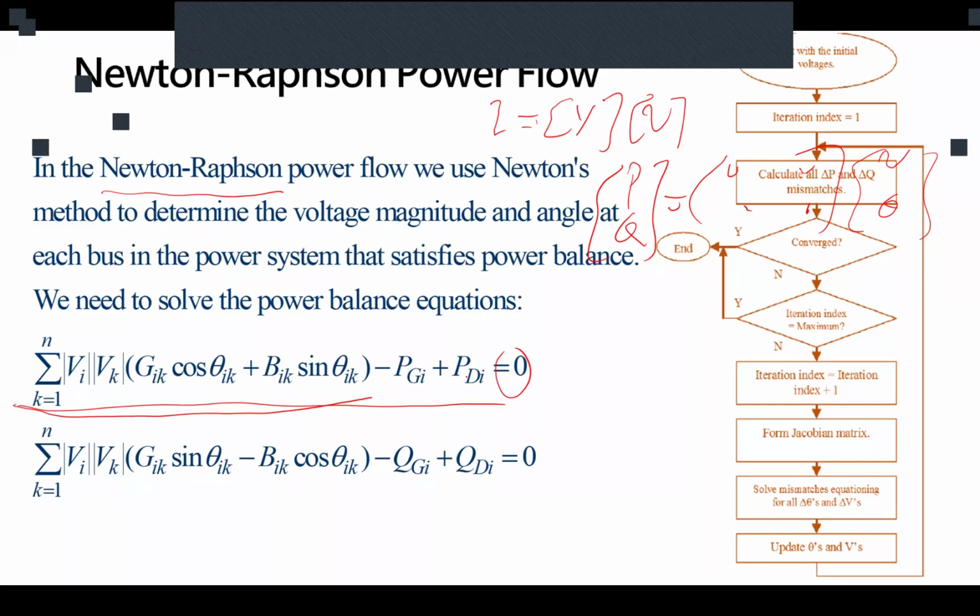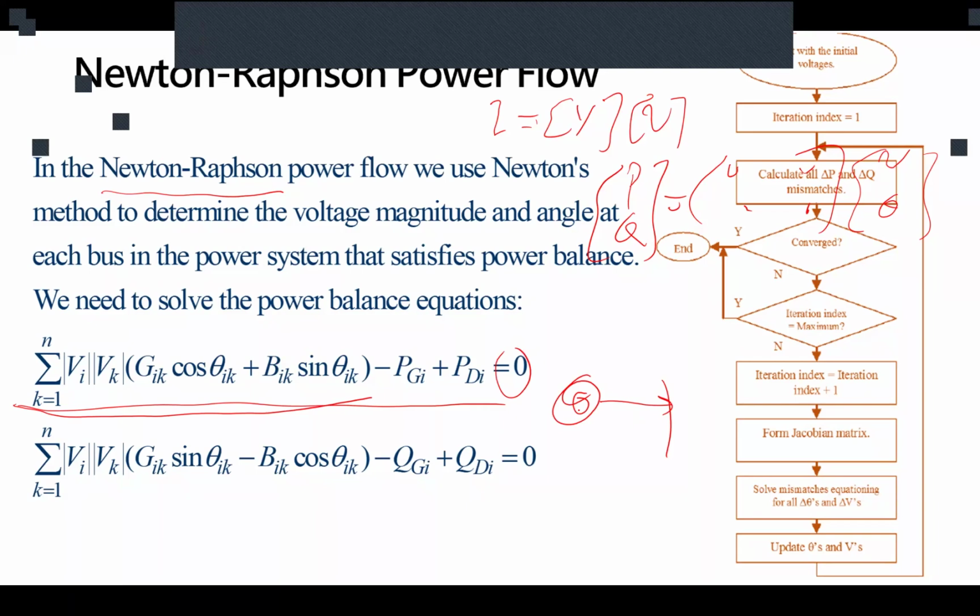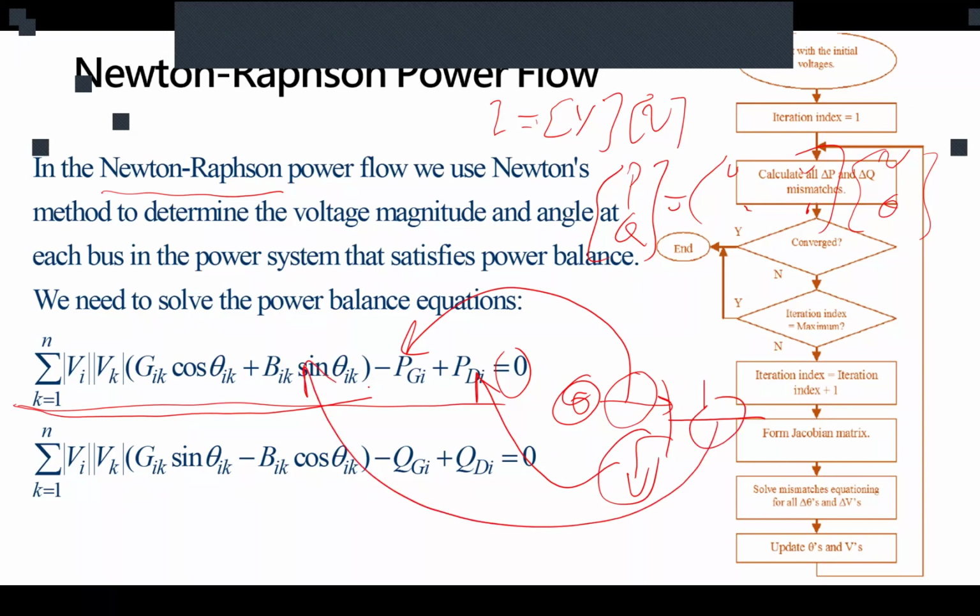When you're talking about demand, is this just like events where it's directly connected? Yes, directly connected to that bus. So basically you have a bus, there is a generator here, there is a load here, and there's a line going out of that bus. Simple KCL says that these currents should add up to 0. This current represents generation power, this current represents demand power, and this current represents the transfer power that goes in or out of that bus based on how much demand and generation there is.